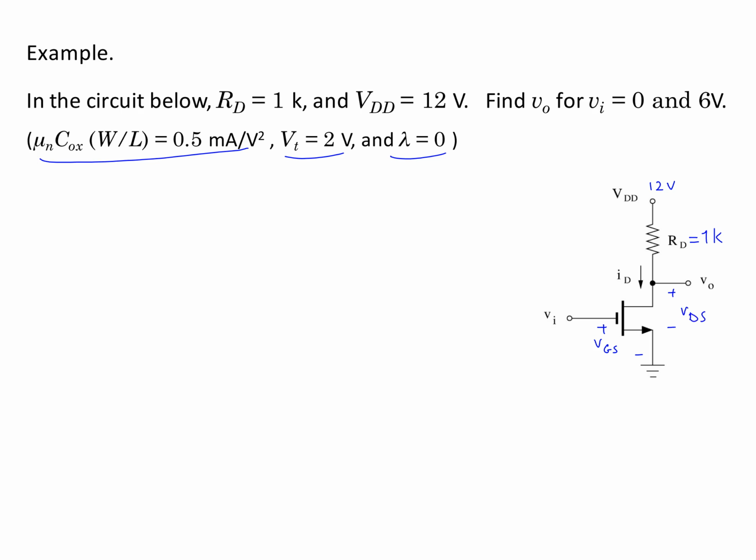And this is an NMOS transistor because by just looking at the direction of the arrow that's pointing outside, it's on the source terminal, and the arrow points outside, so I know that it's an NMOS transistor. So let me write the gate to source KVL. From there I have VI is equal to voltage of gate to source. Good. Then I'm going to write drain to source KVL.